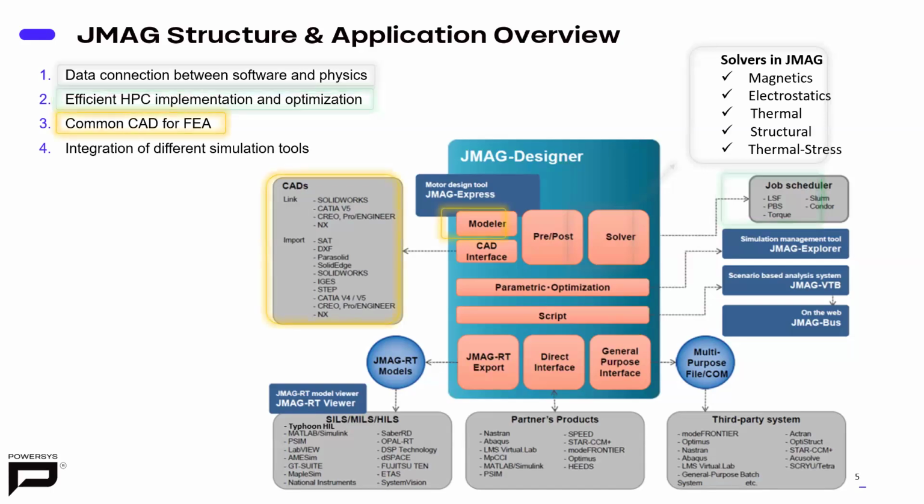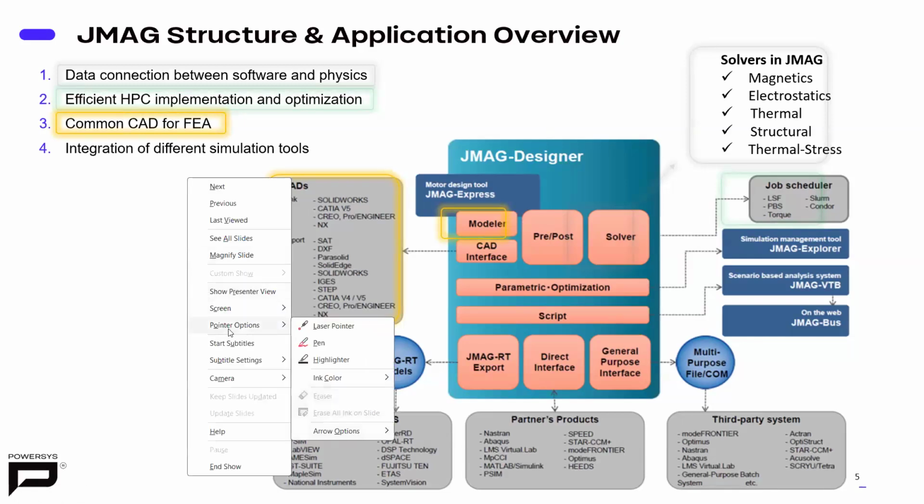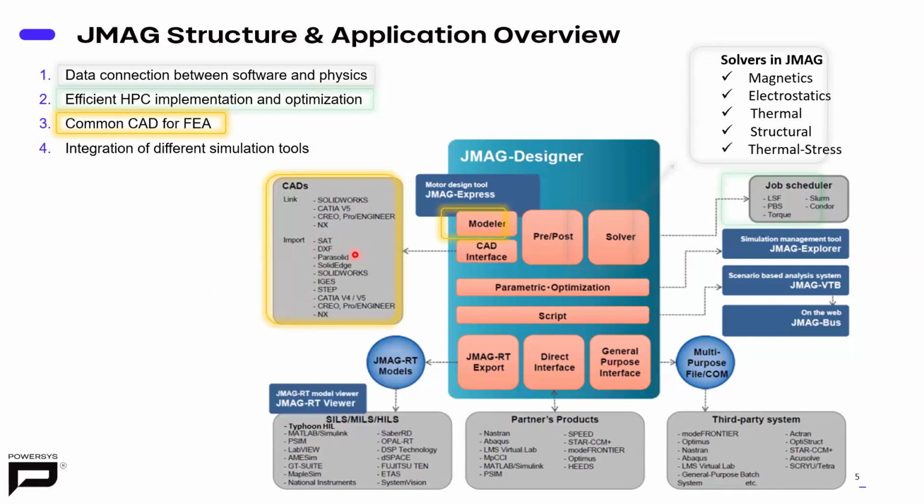Yeah, and also we have a common CAD interface for JMAG Designer, in which software like SolidWorks, CATIA, Creo, and NX, all these CAD files can be imported into JMAG Designer. Also, we can directly import a CAD file in all these formats mentioned here, like SAT, DXF, Parasolid, IGS, STEP. All these formats can be directly imported into JMAG Designer.